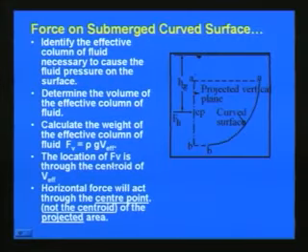Then we can find the location of Fe through the centroid of V effective, and then we have already seen this as far as the vertical resultant force for the various cases is concerned, and then the horizontal force will be just acting through the center point of the projected area, and that also we can determine as we have seen in the previous case. So like this we can determine the resultant force, and where the resultant force is acting as far as a submerged curved surface is concerned.